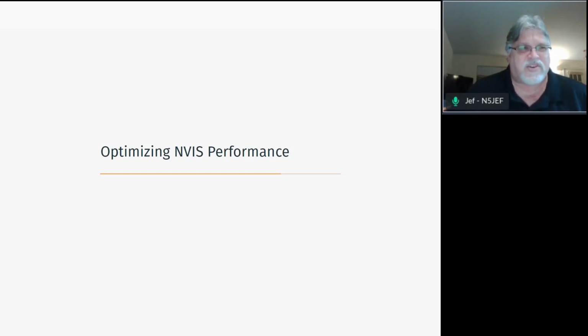The efficiency on 80 meters will be about 50% of a full-length 80-meter dipole. But the cool thing about this is they work extremely well only like 20 feet off the ground. They don't need to be a half wavelength off the ground or even a quarter wavelength off the ground to perform, because it's a magnetic loop, and the field doesn't depend on ground reflections.